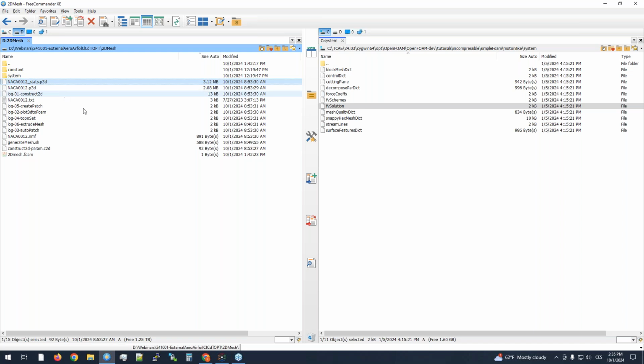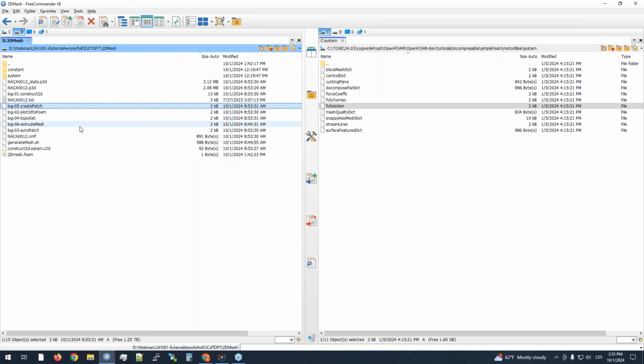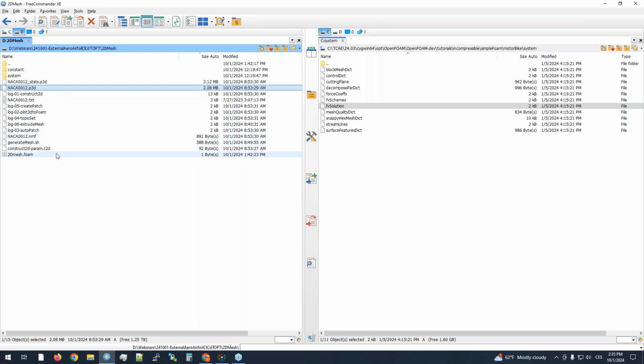and it will give you a mesh in simple Plot3D coordinates, which can then, for example, be transformed into the OpenFOAM format and directly loaded into TCAE, or you can prepare some kind of STL from it and put it into snappyHexMesh. But in this scenario, I would like to show you a very simple example on a 2D mesh. So snappyHexMesh is not the best for creating 2D meshes because implicitly it works in 3D. So many cells are created, and then maybe you can just extrude it, the symmetry part or the empty direction, to get the 2D mesh. But it's more complicated, and this Construct2D, which is open source, can be used very effectively in this application.